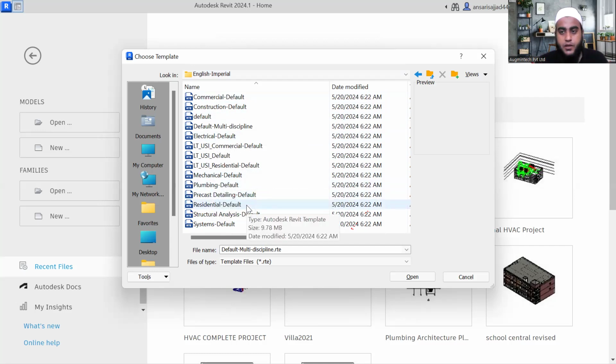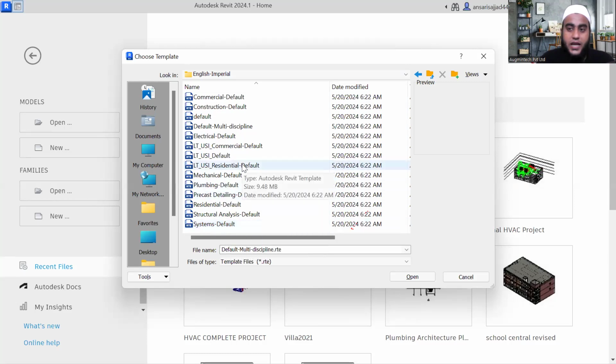And if you want to work in all of these services, see, the system default template is also given. When you open this template, you will get the HVAC template file, plumbing, electrical, everything. So now, you know that we have to perform the heat load calculation. So we have to work in which template file? Anyone, please give me a reply. I want to run the HVAC services, so in which template do we have to run? HVAC comes under mechanical. So we have to open the mechanical discipline, or mechanical template, to run the HVAC services.